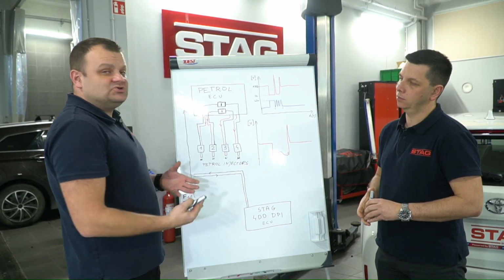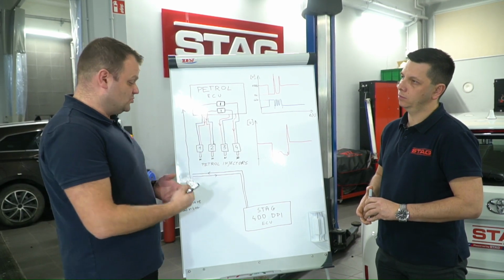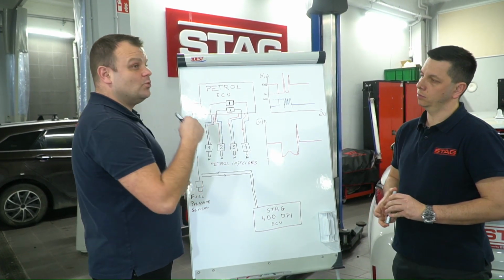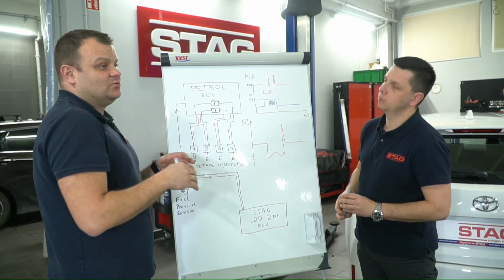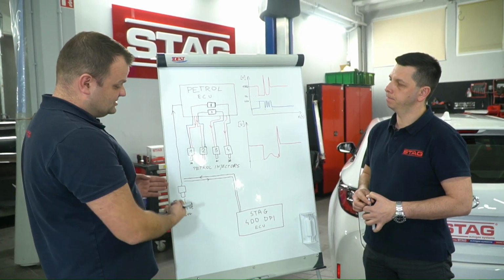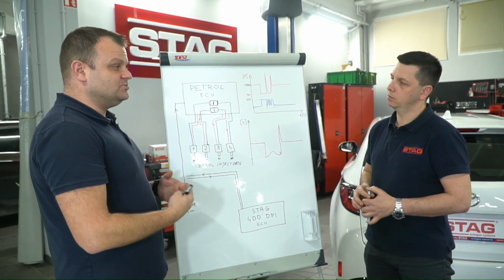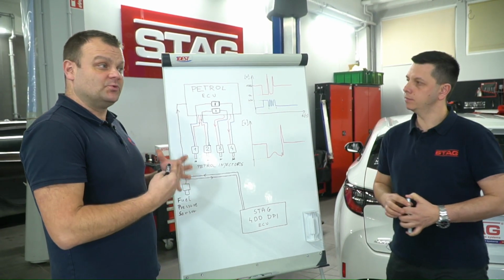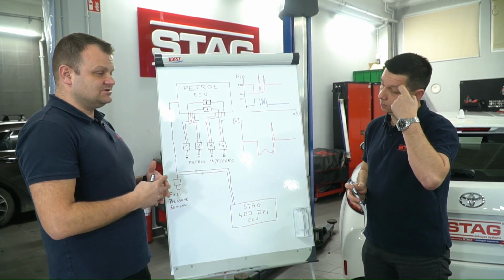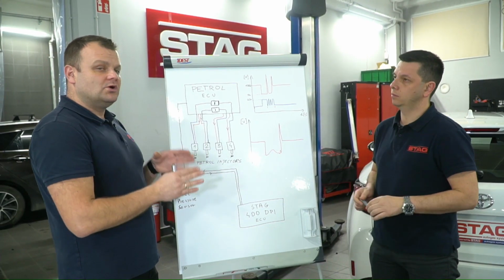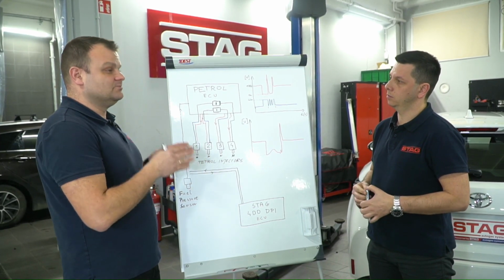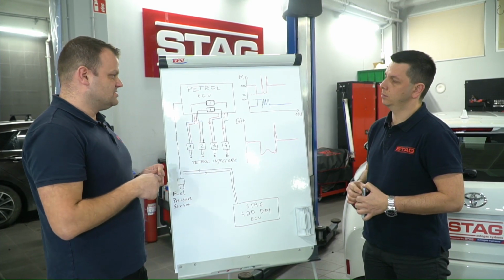So a typical MPI ECU will not properly check what the petrol dosage is and what the gas opening dosage should be, because there is no way to properly measure the petrol dosage. Yes, what we are bringing is the most important thing for calibrating the system. We need to have information on what the proper gas dosage is and what the proper petrol dosage is, of course, to measure it and calculate the gas dosage.